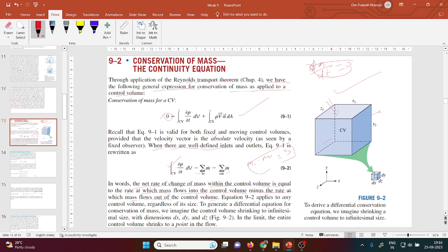This is rho. If you look at what is written here, this is only mass. Rho is kg per meter cube, t is time in seconds, and this one is volume in meter cube. So meter cube cancels, and that is the mass flow rate. This is mass in, mass out, and the rate of change. The dot is given for mass by time: mass by time in, mass by time out, and how the rate is changing.